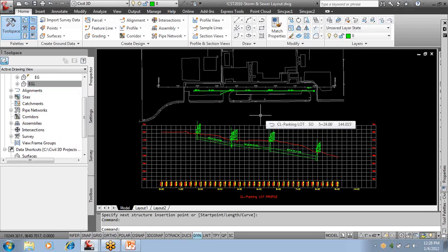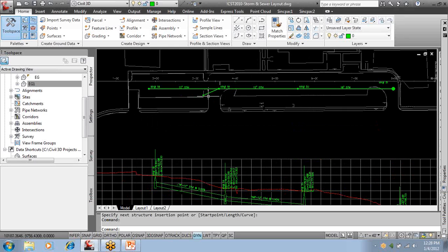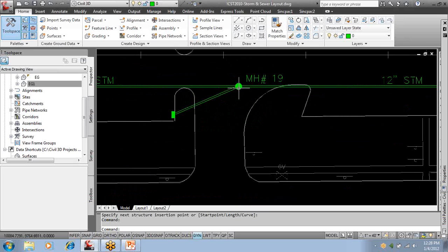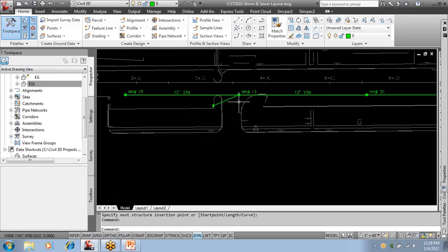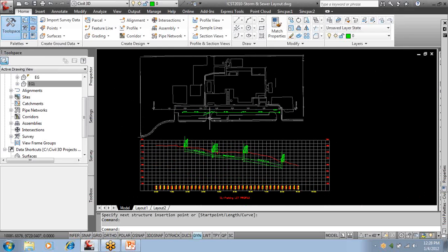All right, we picked it, we looked at the ribbon. We get a lot of information also from the drawing just by moving the cursor over it. What manhole number, what size. There are a lot of different information advantages just by giving it to you basically without you even having to do anything. Creating the surface, we went to the alignments. You noticed the points toolbar. You had the alignment toolbar, profile toolbar. We had a pipes toolbar. You see how everything's isolated to those different things.